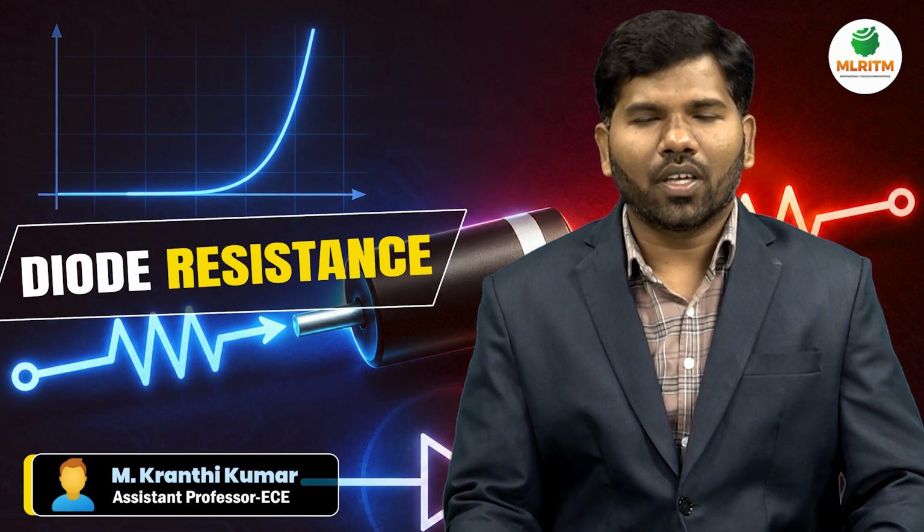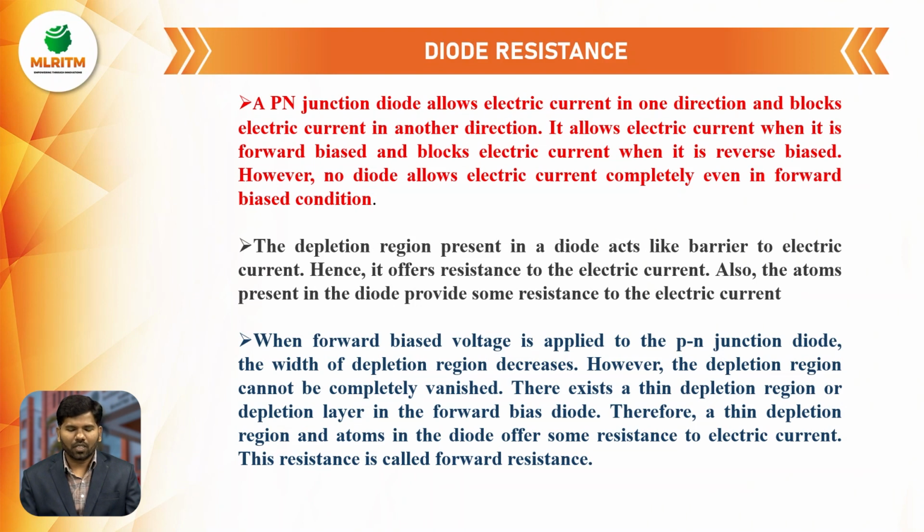In the previous lecture, we discussed the voltage and current characteristics of the PN junction diode. In this lecture, we are going to discuss diode resistance. The topic name is diode resistance. A PN junction diode allows electric current only in one direction and blocks electric current in the other direction. When we connect the PN junction diode in the forward bias condition, it allows the flow of electric current. When we connect it in the reverse bias condition, it will not allow any amount of current. So it works only in the forward bias condition.